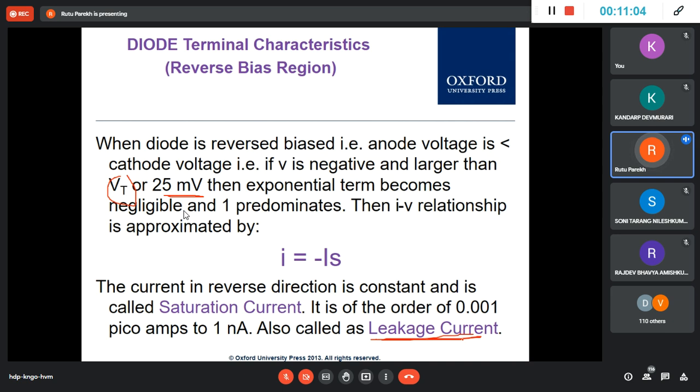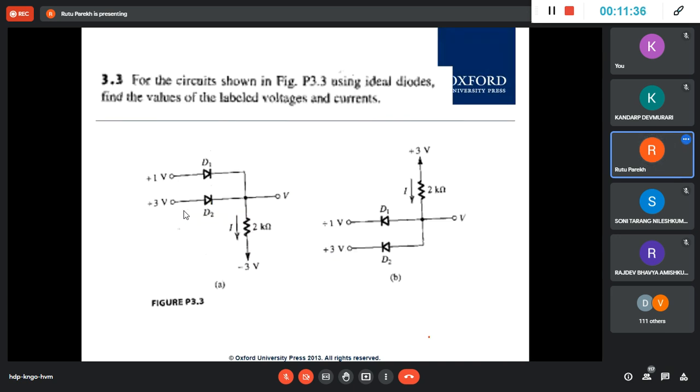But that's not possible, because this is a chunk of material, and the electrons get a medium, it is very continuous, there is no breakage, right? If there is one piece and then another is at some distance from there, still the charge can travel. Even in vacuum it can travel. So that is always there, but that's okay. It's really a low value, and we say it's leakage current.